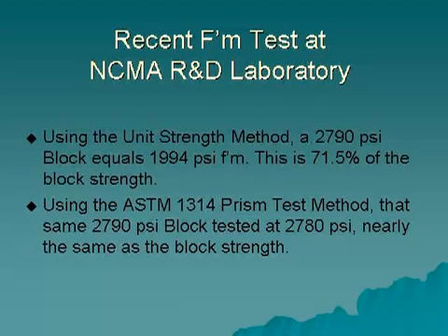Pre-testing by the prism strength method can provide design information that can be used for more sustainable masonry. And at the very least, test reports shown here do reveal more value than using the unit strength method.